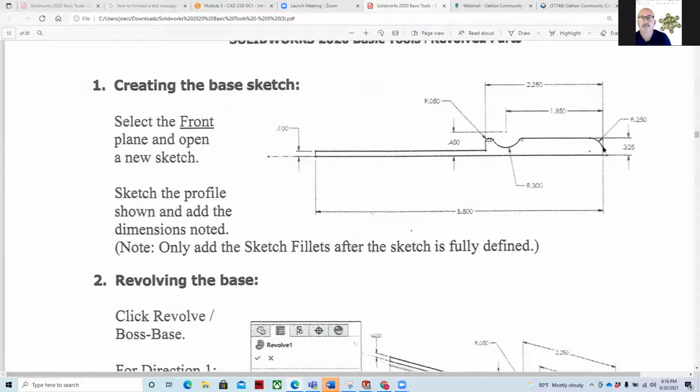And you can see this is where the origin is located. And then we go straight up, slight arc, straight over. And what I did is I just created a circle and then I trimmed it out and then I filleted it to create that geometry. Same with this area, I created straight lines and then filleted it with 2D geometry.